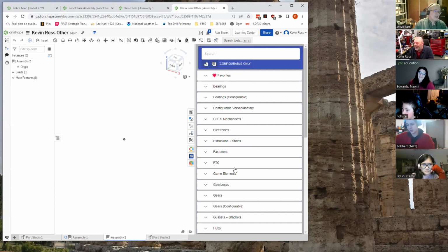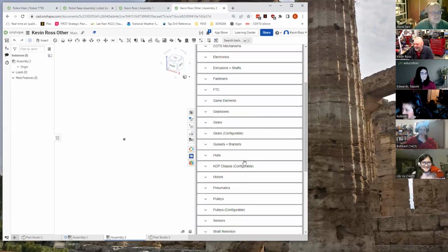I see things like RoboRio and simplified RoboRio. The one it doesn't have is RoboRio with clearance for all of the wires that are coming off of it. You need a RoboRio with a larger box around it, and especially a power distribution panel with a larger box around it that reserves clearance for all those heavy wires. I'm with you. Having said that, wow, talk about a number of variables. Oh, perfect. Thanks for pointing that out. I wasn't looking to the right at all.